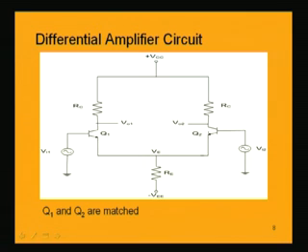Basically this is the internal circuit, and we will have a number of differential amplifier stages in the OpAmp. That means we are considering only a single differential amplifier circuit, but there will be a number of stages of these differential amplifier circuits, directly coupled, and the overall gain will be very high because they are cascaded, in series. After all the cascading stages, whatever we get will be the gain of the OpAmp. So, it is a very high value.